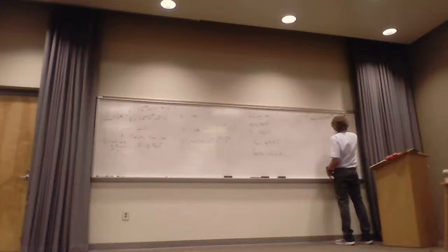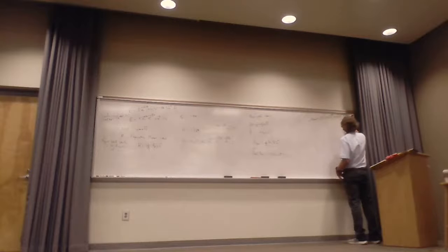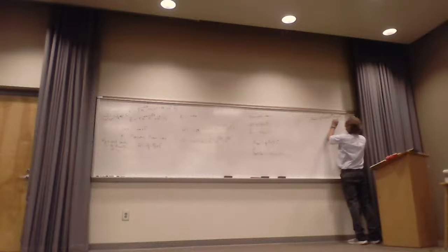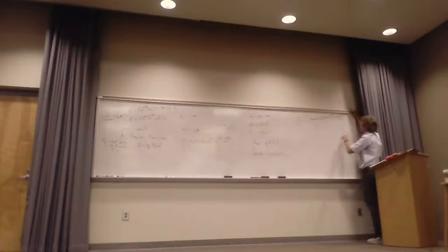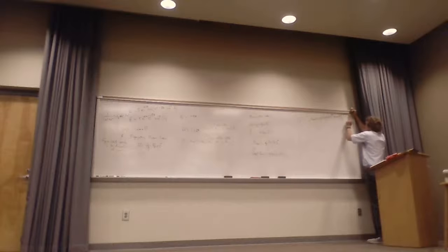Well, H is going to be equal to E naught, I'm going to conjugate that, e to the minus alpha Z, e to the minus j beta Z, divided by magnitude of eta naught. Then the angle comes up here as e to the j, or an angle of eta naught. That's the intrinsic impedance here and here. And this would be in the AY direction. Let me try to explain what I've got here. I take this E field and divide it by the intrinsic impedance. I change the direction to be Y.